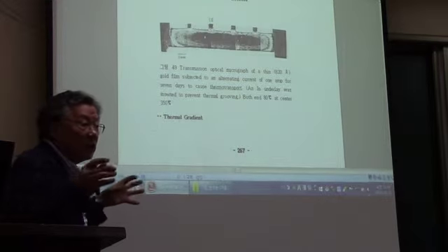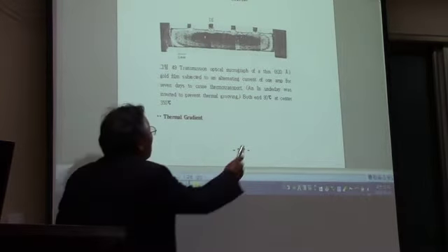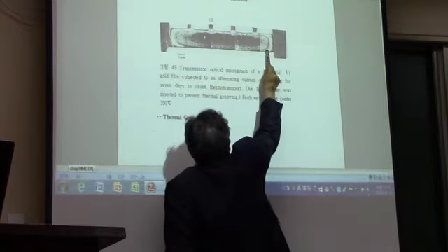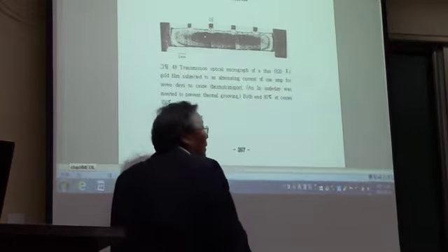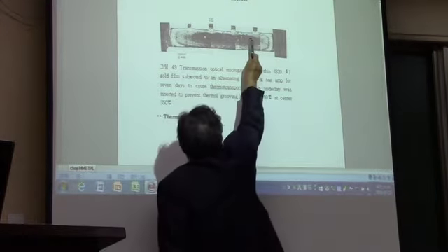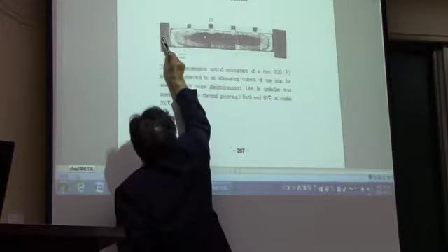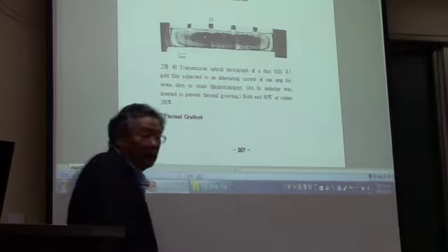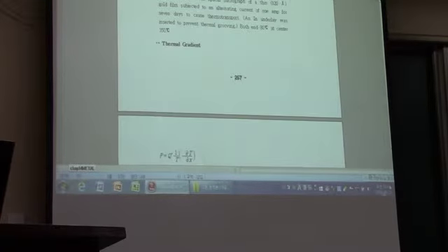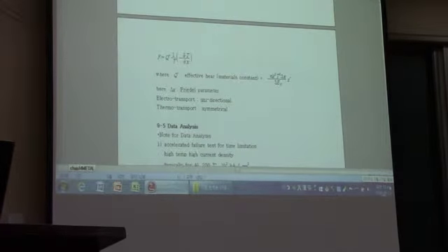And you can see with the optical microscope the thinning of metal lines, okay, because of the thermal migration. And here, this part, the white part, the gold is going to move. It has a depletion, while you have accumulation in the dark side, okay? So that is the thermal migration.